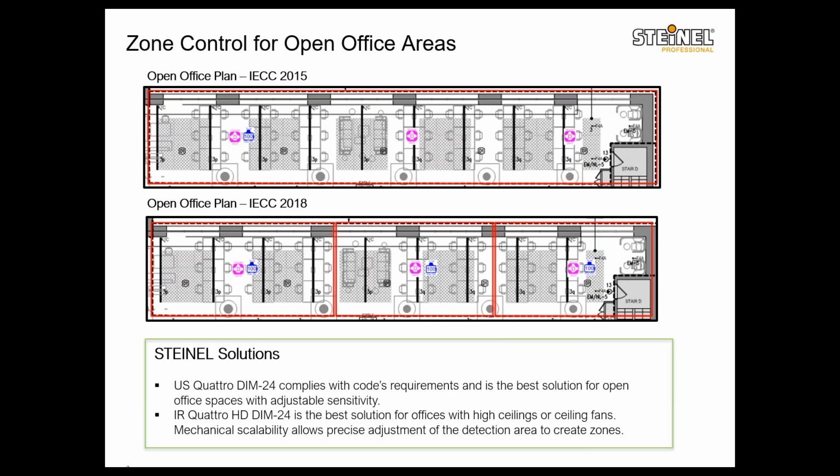And with our IR Quattro HD, we have the mechanical scalability option in the sensor that we can use to crop the detection coverage exactly to the size of the detection zone, based on mounting height and the zone size. So we have 2 very good solutions here that give you flexibility depending on your office type, and either solution meets the codes pretty easily.